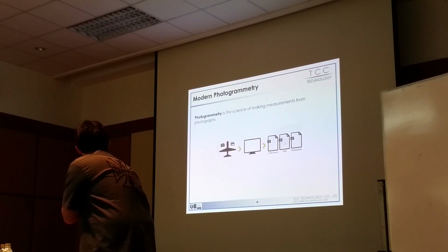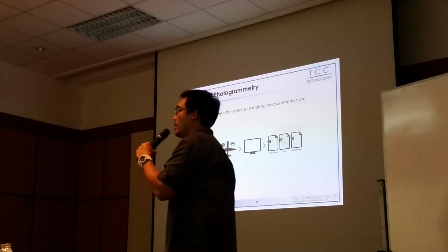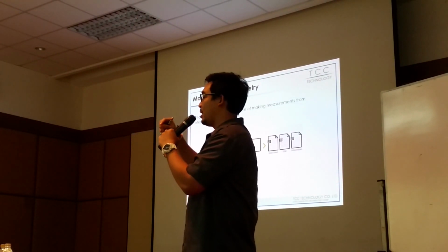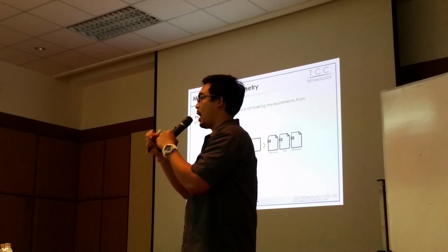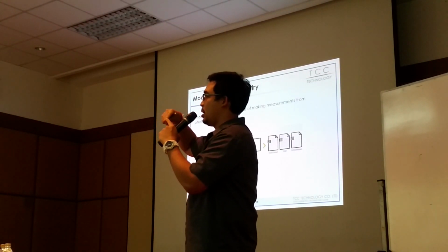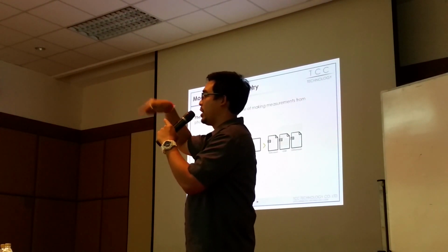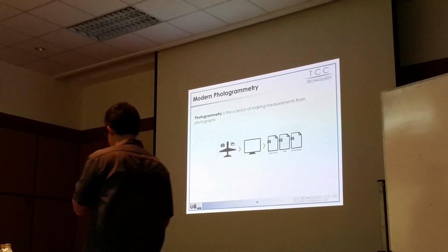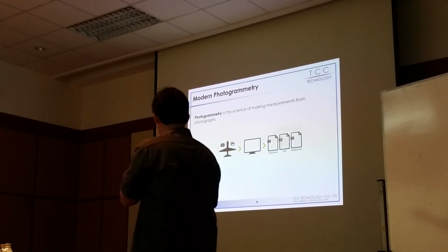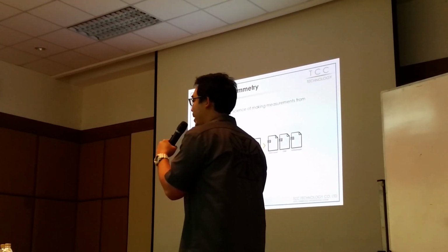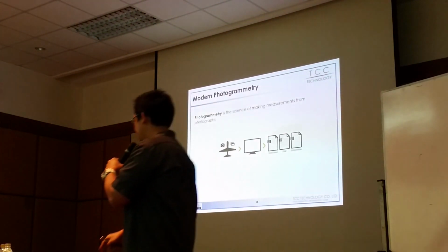And we also get the digital surface model. When we have the point cloud, we can calculate the triangulated irregular network, where we create the smallest triangles between each point to create the surface. So from normal images, if we want to produce this kind of information, we need some technique.